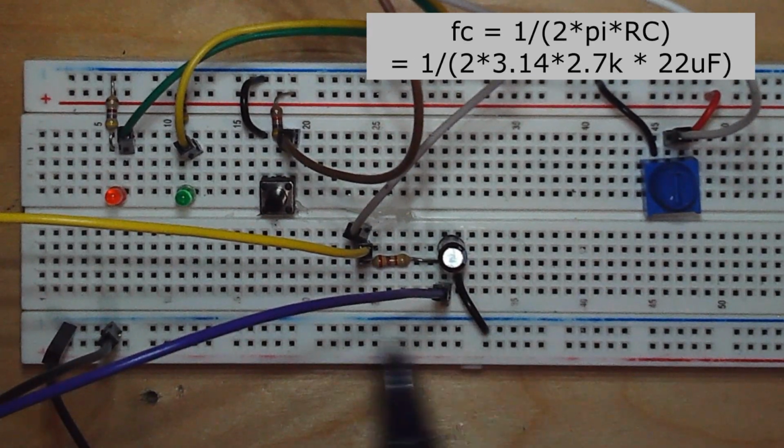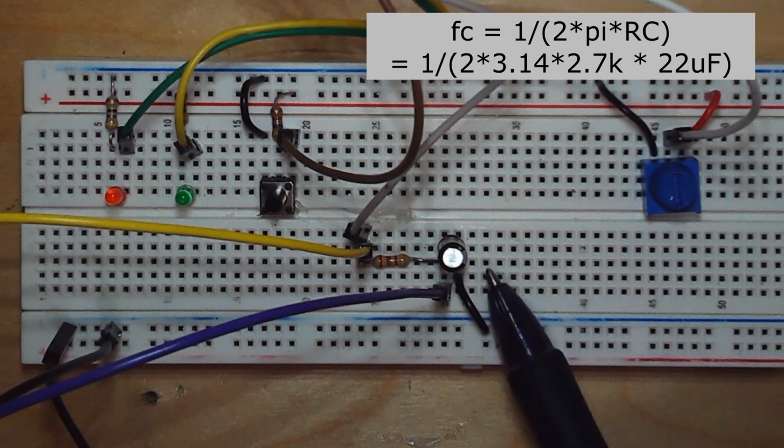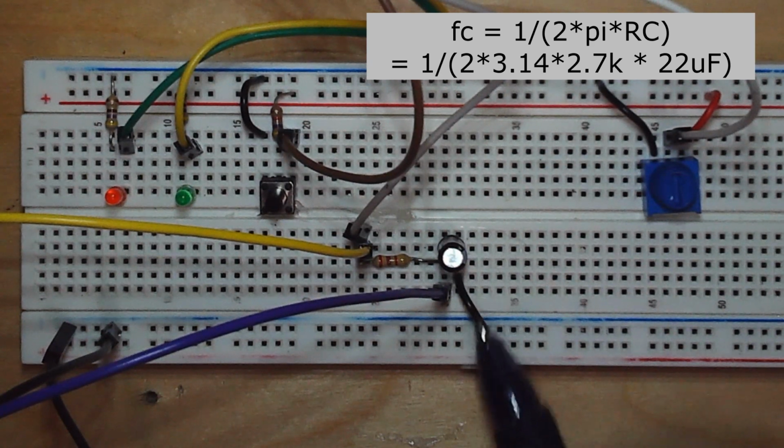Over on this part of the circuit is the low pass filter. It is made up of a 2.7K resistor and a 22 microfarad capacitor. Be aware that this is a polarized capacitor, and the white stripe has to be on the negative side, and typically the longer lead of the capacitor is the positive side.